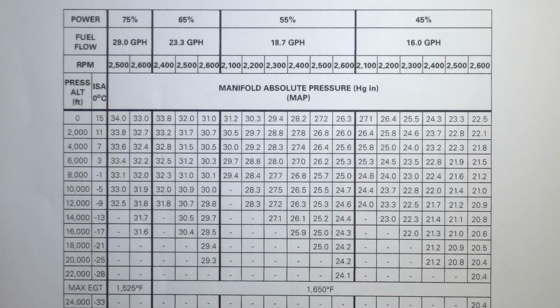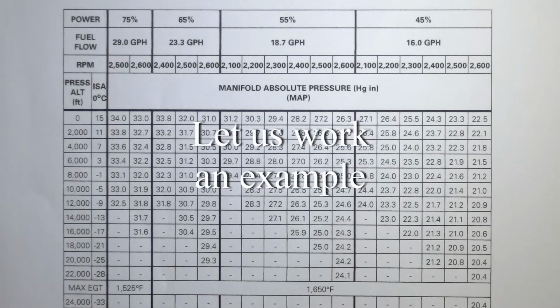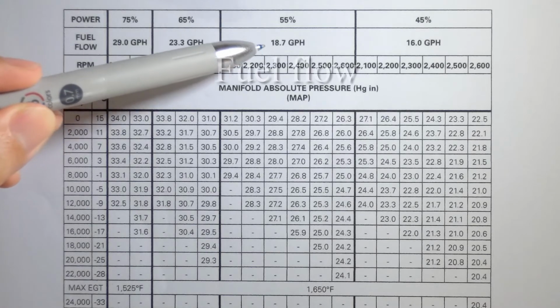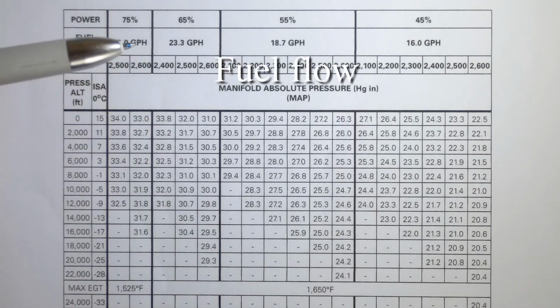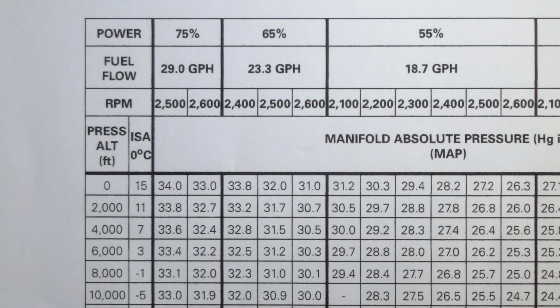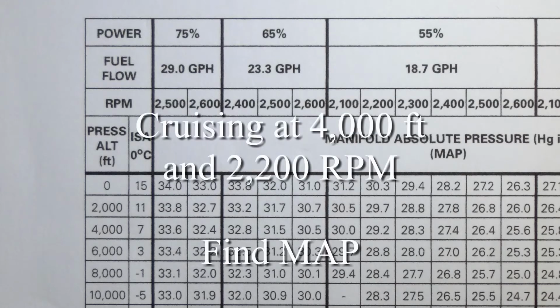How then do we use this chart? Let's find out by working an example. Let's assume that we will cruise with a power setting of 55%. And at 55%, we can see that the fuel flow is 18.7 gallons per hour. Assume we want to cruise at 4,000 feet at 2,200 RPM. What would be our manifold pressure?